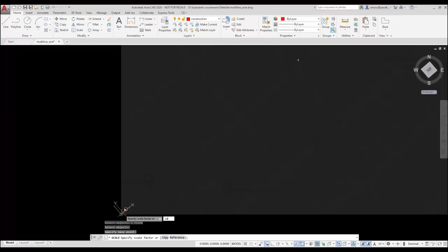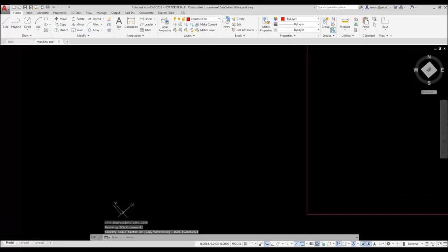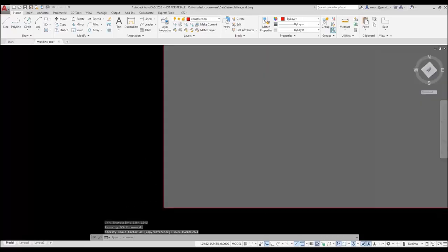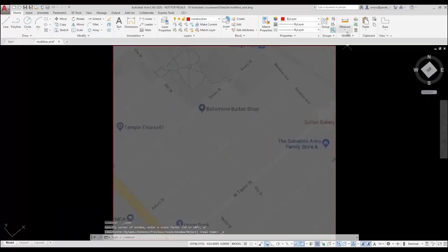I type 'CAL to indicate that I want to use a calculation. I'm prompted for an expression. I type 336 divided by the number I got when I measured the street. Now when I remeasure Asbury's street width, I should get a number close to 336.